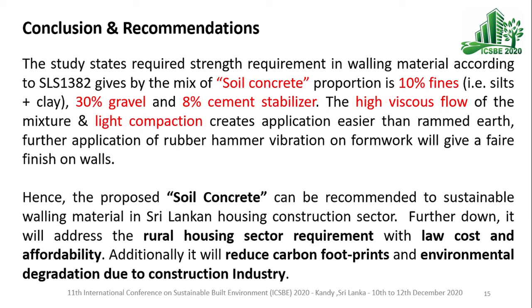As a conclusion, the study recommends a soil concrete proportion of 10% fines, 30% gravel, and 8% cement stabilizer with high viscous flow, using a light compaction method. We can recommend this for rural housing sector requirements with low cost and affordability, and reduced carbon footprint and environmental degradation due to the industry.